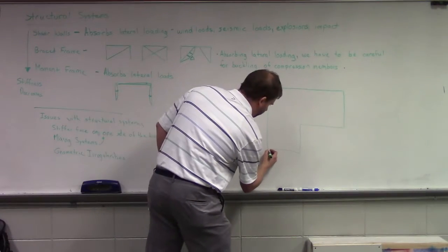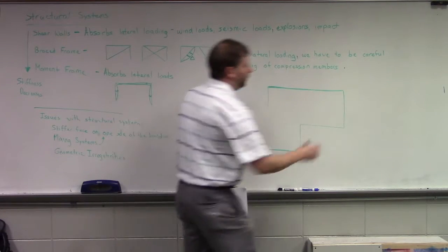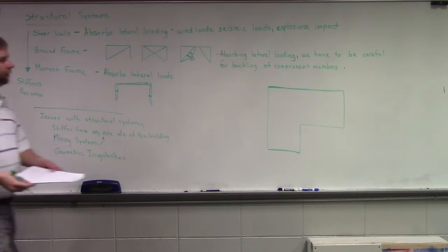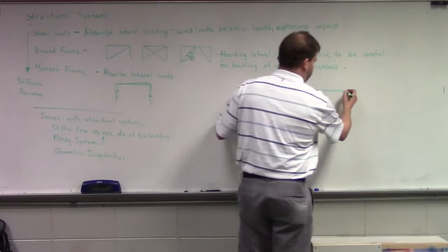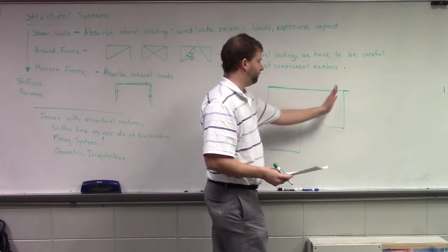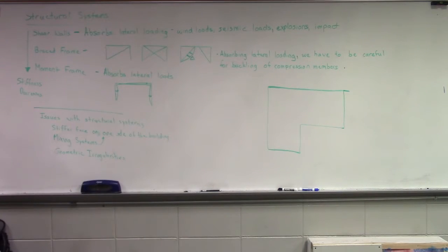But if we have a shear wall here, and we have a shear wall here, what could potentially create an issue? This wall right here is bigger. You have greater distance, so you could potentially get greater deflection here than you would here, right? So you could have some sort of issue, potentially in your foundation, potentially in the wall itself.